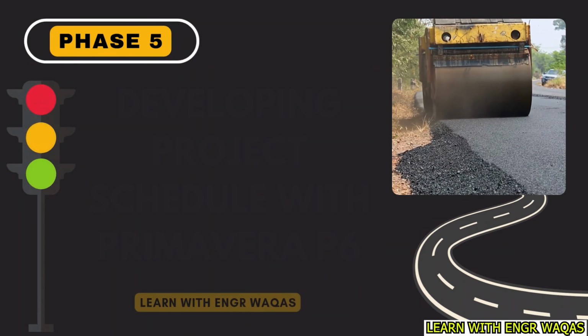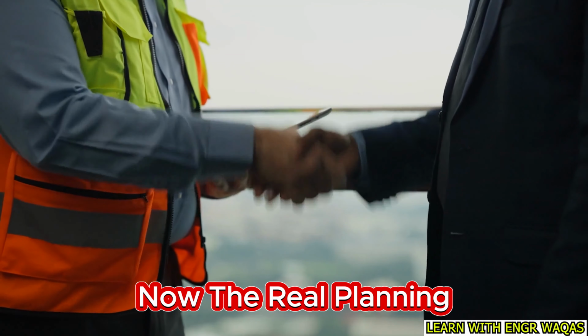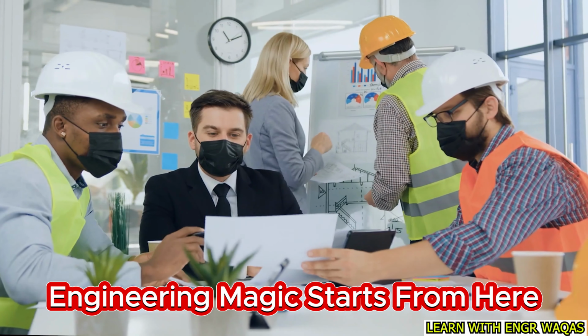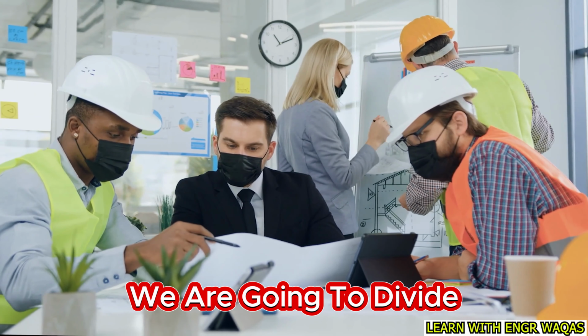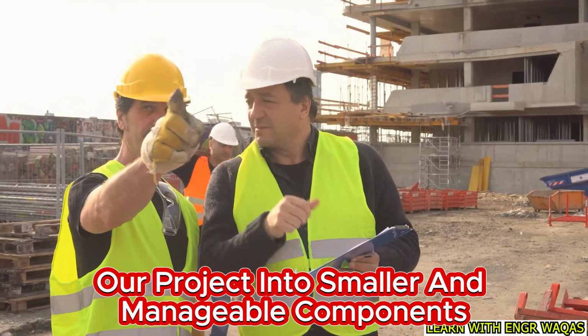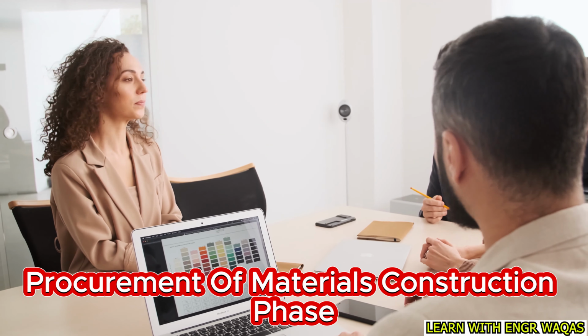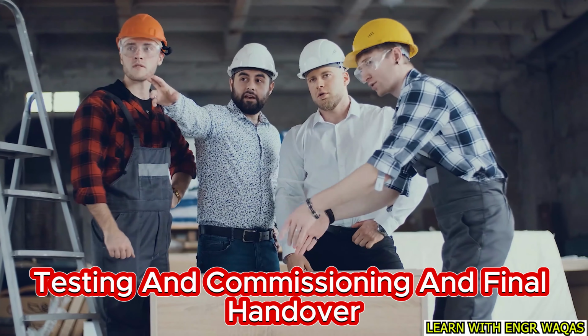Phase 5. Developing the project schedule with Primavera P6. Now the real planning engineering magic starts from here. We build a work breakdown structure. We are going to divide our project into smaller and manageable components. The WBS should include engineering and approvals, procurement of materials, construction phase, testing and commissioning, and final handover.